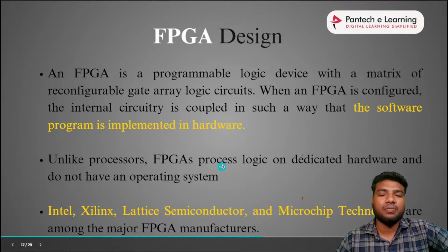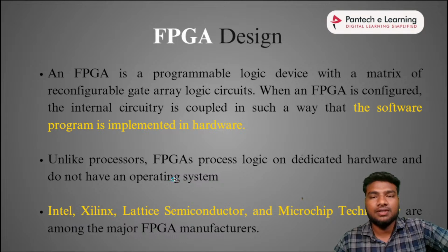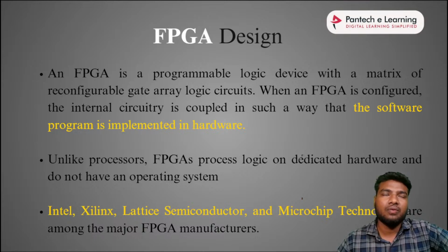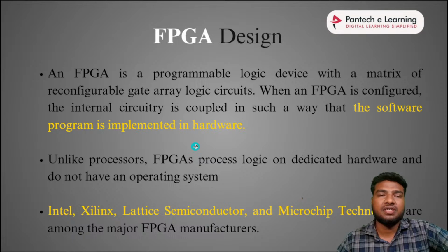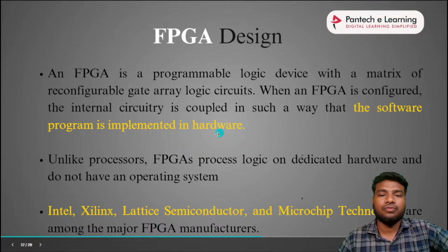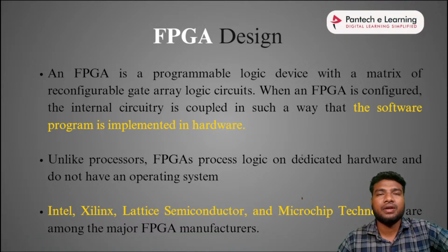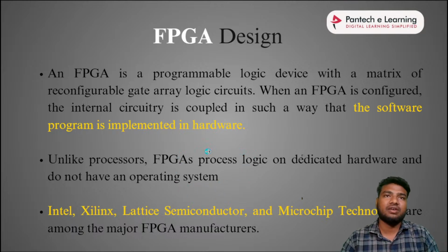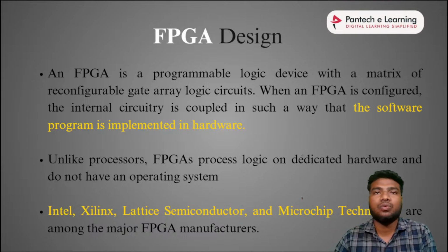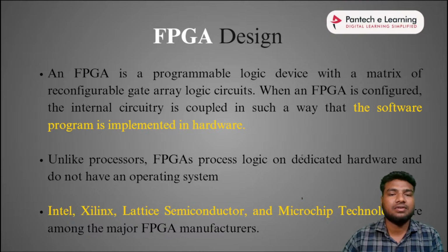There is a PYNQ board in the market, and there is also a PYNQ OS in the market. In the FPGA board we insert our SD card with the OS, and then based on our feature, the Zynq PYNQ board peripherals can be used for edge detection, object detection, image processing and so on. We can use an OS in separate FPGA boards like PYNQ and Zynq FPGAs. Why? Because Zynq and PYNQ FPGAs have an SoC inside the FPGA, so we can use them for high-end usages like image processing, AI projects, machine learning.